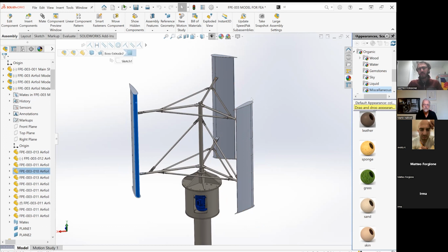And people have done all sorts of different schemes. They'll use twisted blades that are more of a helical shape so that they basically smooth out the forces, because the forces are continuously changing. It's like a three-phase diagram, right? So you have three continuously changing phases of forces or torques that are rotating around, and by making it somewhat helical, you actually are extending across a zone of angles rather than one specific angle, right? Because this is like a very discrete spot compared to on a helix. So that's kind of the general basis for this.